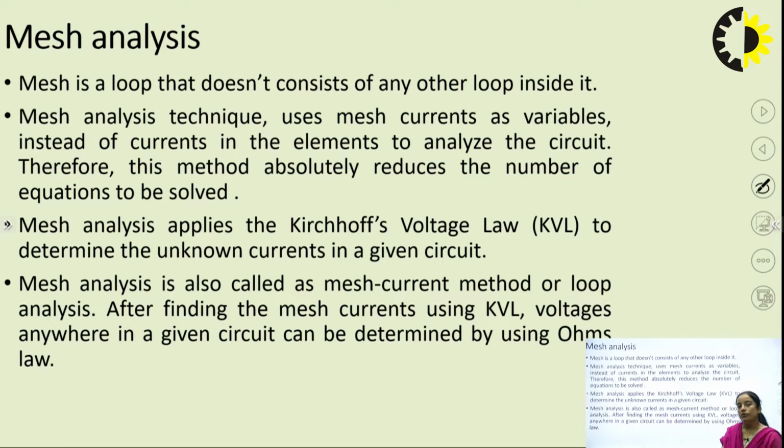If we need to calculate the power absorbed in any element, then having calculated the current through it, we square that current: I squared into R gives the power absorbed by that network element. Current into the resistance of that element gives the voltage drop.